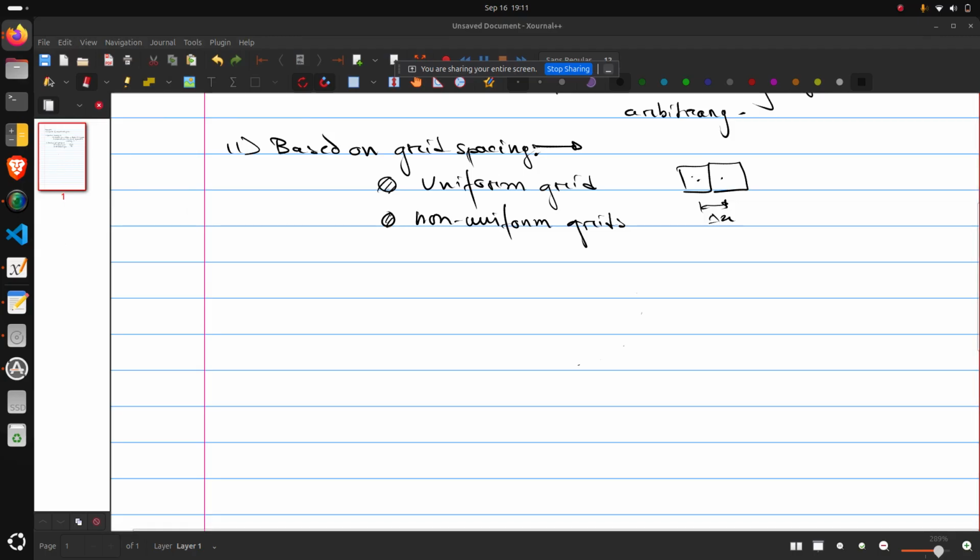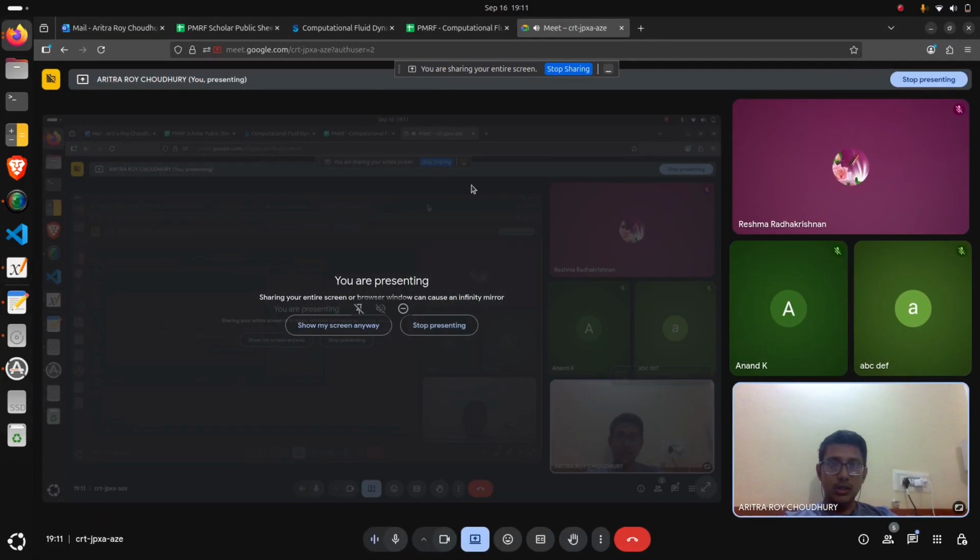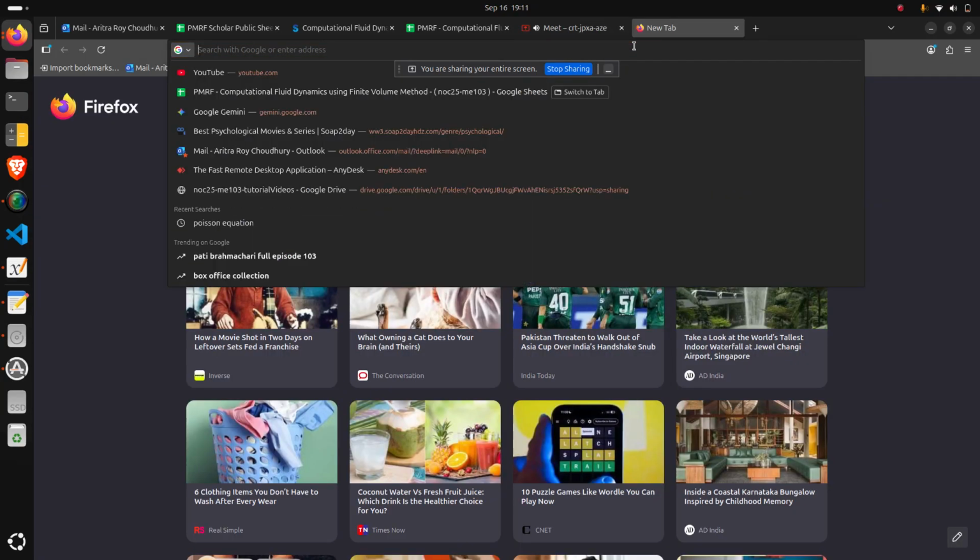So in general fluid dynamics cases which involve some solid boundaries or walls, we'll have very fine meshes, very fine resolution very close to the wall, and as we go far away from the wall, where the influence of the wall is no more, we'll have much coarser resolution. Okay, so let me just show you an example. This will make it clear.